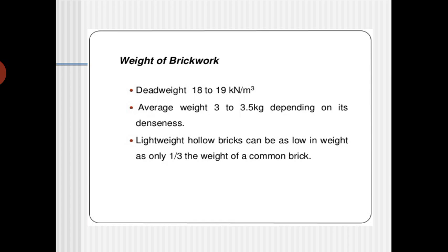So normally, if you see the weight of the brick, the dead weight of the brick is 18 to 19 kilonewton per meter cube. Then the average weight is equal to 3 to 3.5 kg depending on its dimensions.